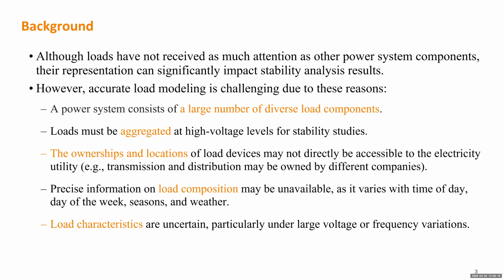The characteristic of load has some uncertainties. And the data we have to model the loads usually are collected from normal conditions, right? But why do you need to do a stability study? Because you want to cover abnormal conditions, but you don't have enough abnormal condition data. You can only somehow predict what abnormal conditions can be. But the load model is pretty much based on normal condition data. So there are those challenges, which means we don't really have to model the load very accurately. And actually, it's not practical to do that.